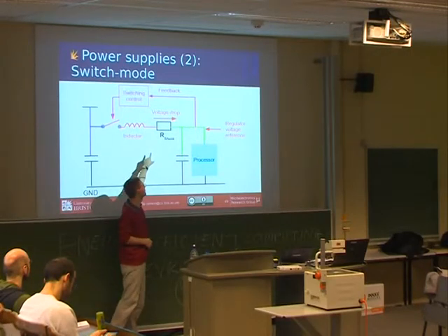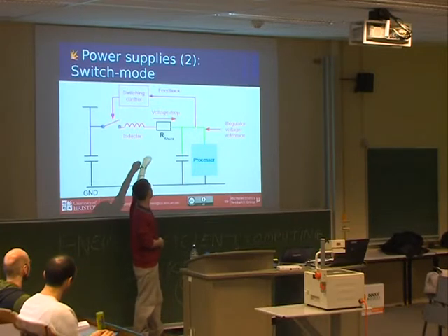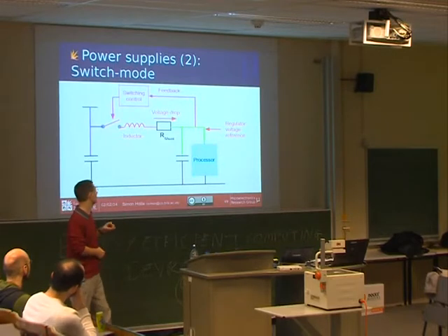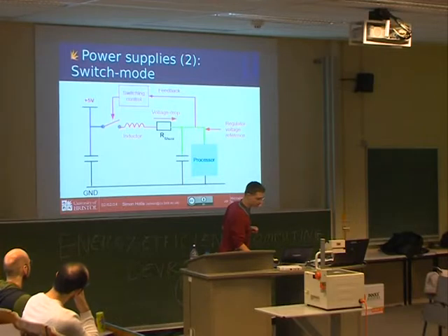So you put the shunt resistor in. As long as you put the shunt resistor before the feedback, and it can be in either order with the inductor, and in either order with the switch, then you will get feedback that ensures that the voltage across there is adjusted for automatically. So what that would look like in the same example is 5 volts goes in.